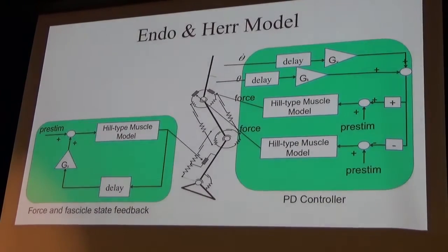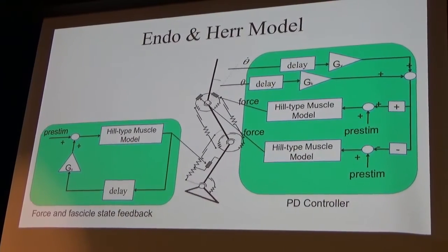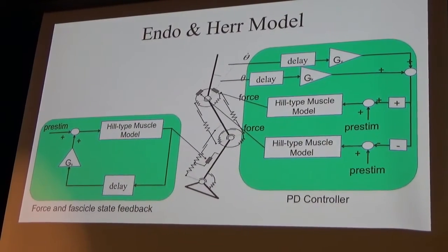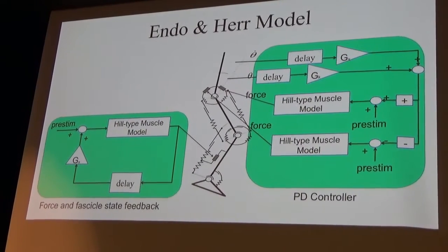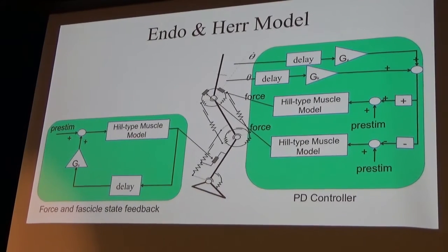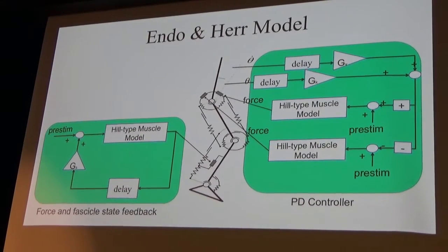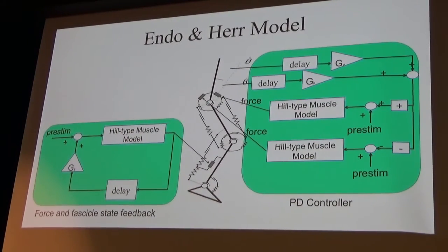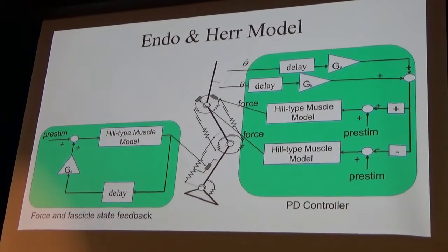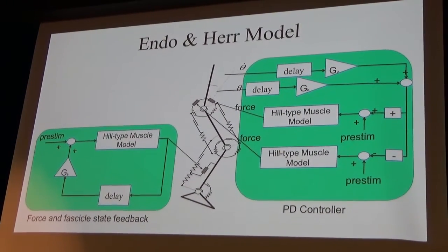For dynamics, we have to apply reflex models to the muscles, hill-type muscles being modeled in the limb. They are the soleus muscle, a monoarticular muscle of the ankle, and two monoarticular hip flexor-extensors. So in the field, it's been observed or hypothesized that the dominant feedback loop of the soleus muscle is a force feedback. There's position and speed feedback as well, but force is dominant when the foot is in contact with the ground. So we apply that in the model.